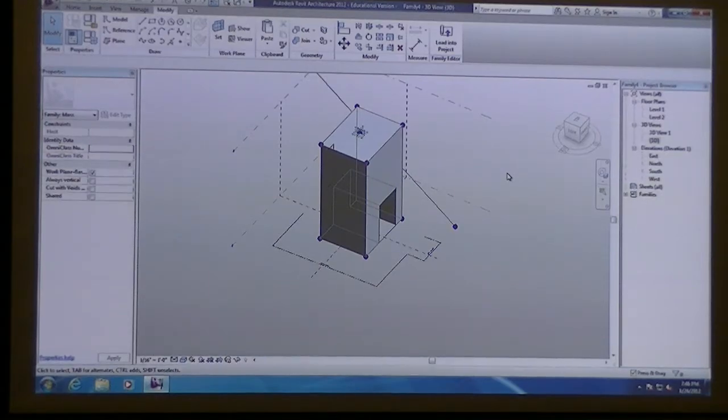That sloping surface is going to represent stairs. If you have any kind of stairs that you think you're going to have in your model, don't worry about modeling that plane, because we're going to be bringing all this into a project environment where stairs are automatically generated from one surface to the other. So you don't need to model stairs or ramps or anything like that in the conceptual design environment. What we want, the goal is to generate all of your surfaces. Again, remember we're using this as an underlay that we're going to eventually apply all these tectonic structures to and further develop this into a very complex tectonic form.